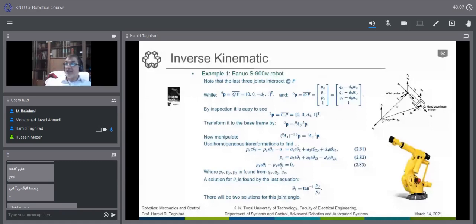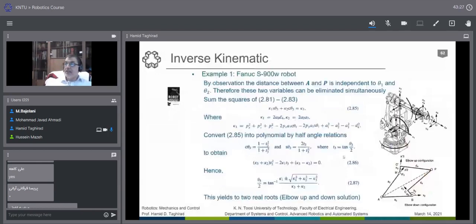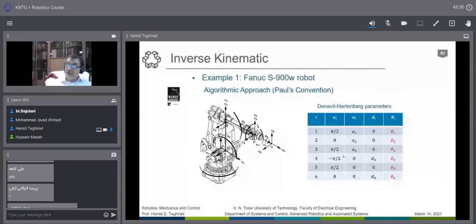now we can work on theta 2 and theta 3. Now you can also use the mechanical structure, the second important thing, to find theta 2 and theta 3, or somehow eliminate some problem here. You can see that as you see this point, the first one was very easy, that P1 with respect to x3 is d4 only in the direction of z4. This makes our life much easier to find theta 1.